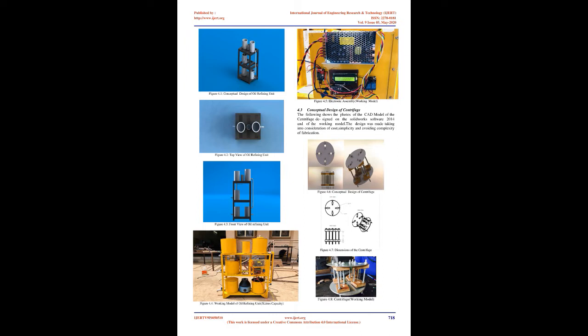The recycling process started with removing the contamination from the used engine oil. Glacial acetic acid was mixed with the used engine oil using a ratio of 0.8 ml acetic acid to 10 ml used engine oil. This was followed by stirring in a closed container at room conditions, room temperature and pressure, for 1 hour. The mixture was left for 24 hours at room conditions and then underwent centrifugation for 1 hour to separate the base oil from the contaminants.